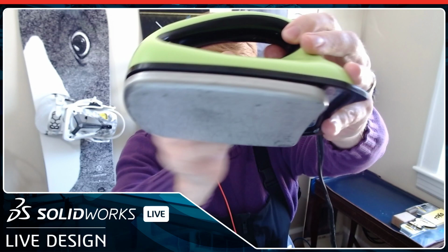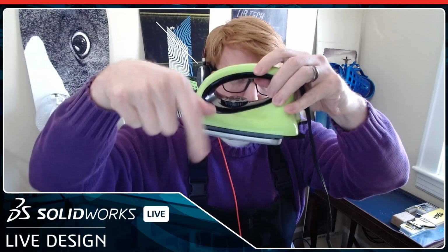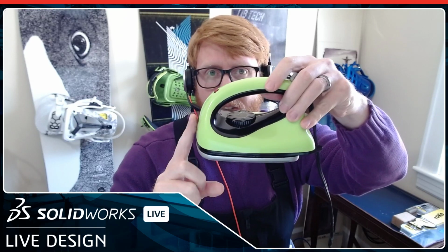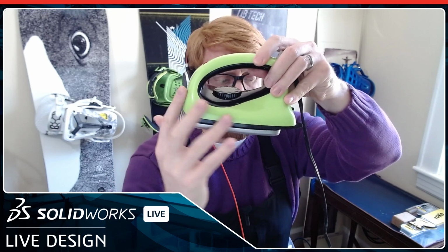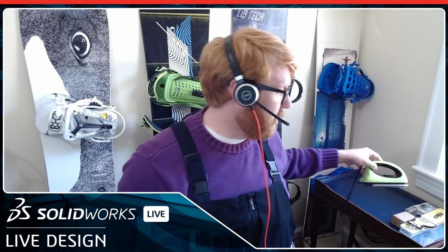There's a screw right there, which I think is pretty clever, honestly. So this whole piece can come up through, and it doesn't need anything special. But I know that this is the pull direction, and I'm assuming that there's probably at least 2 degrees of draft on this thing. So that's what I'm going to do. I'm going to give this thing 2 degrees of draft so that I ensure that this entire thing all the way around has 2 degrees of draft on it.